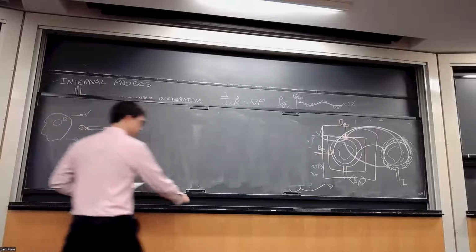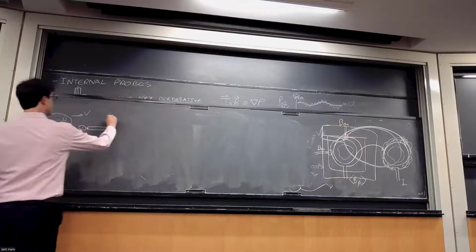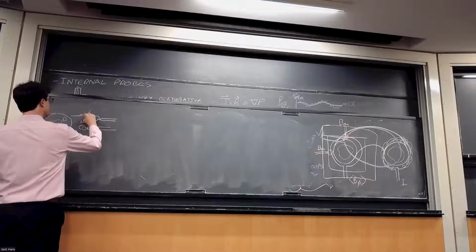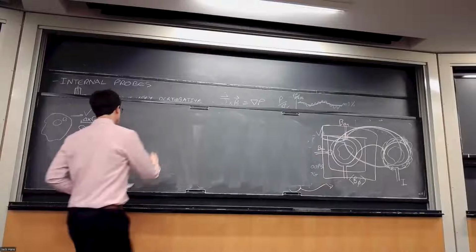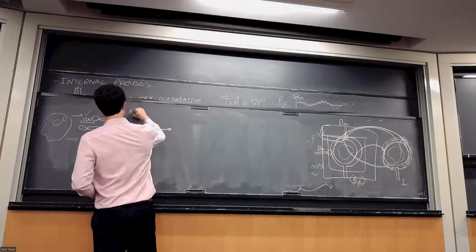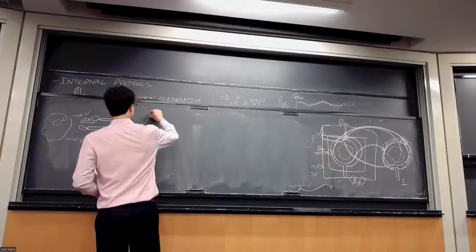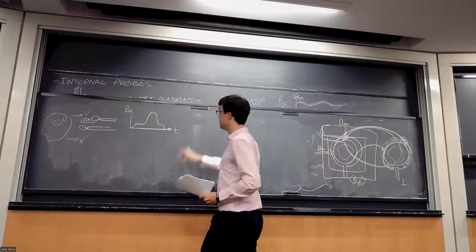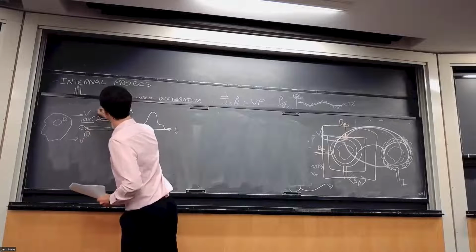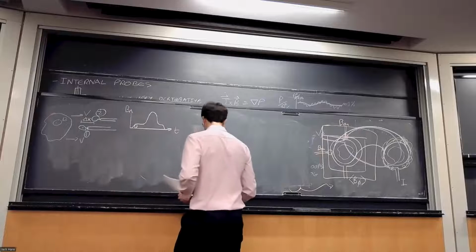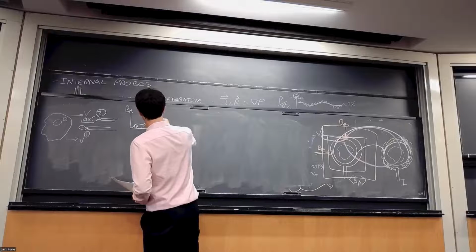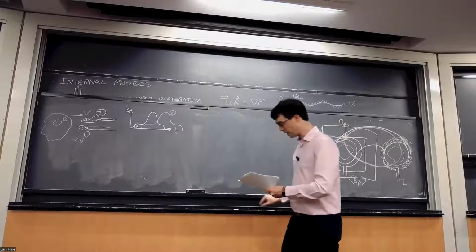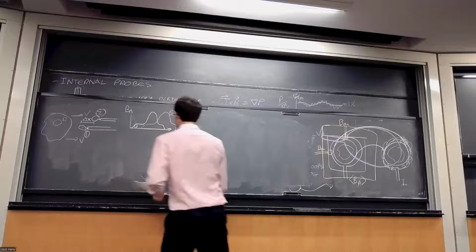And if you have a set of these B dot probes, for example, if you have one here, and then you have one up here, and they've got some separation, delta x like this, the signal that you'll measure on the two probes will be delayed. So if one probe goes like this and gives you this magnetic field as a function of time, well, that's 1, this is 2, and the next one goes like this, you can do some rather neat tricks and identify similar features in these two signals.